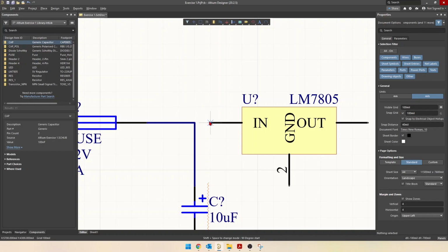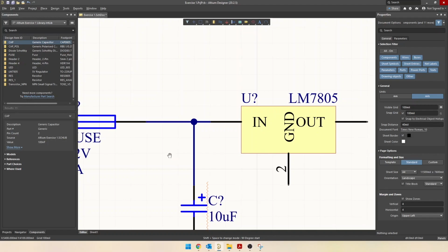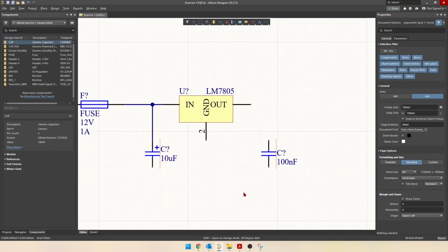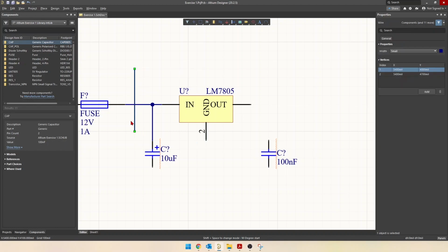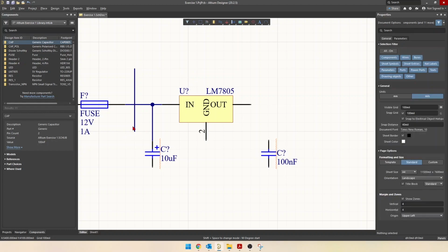And then we're just going to place another wire to fix that. I recommend going from the snap point to the wire here, and you can see this little round circle. That is called a junction, and that tells you that this vertical wire here is connected to this horizontal wire. There's an electrical connection there, just for ease of readability. If I had a wire going across here that wasn't connected, it would look like this. There'd be no junction. This wire is not connected to this wire.